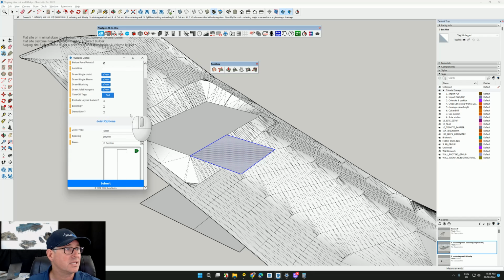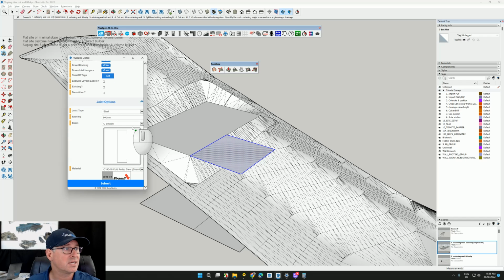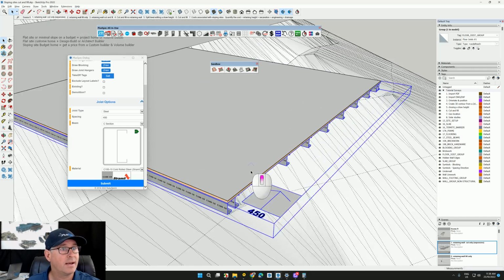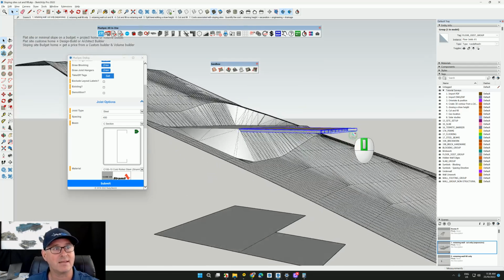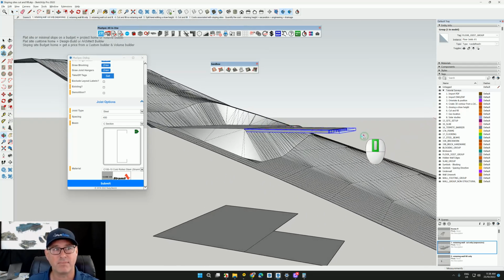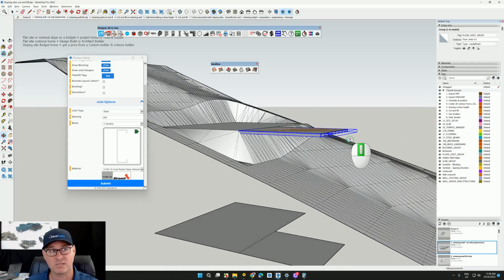We don't need a ceiling. Steel C-sections at 450 centers, say. And go submit. Right. Now I have joists in there. Now I can actually put steel across there and beams down there, because it's probably going to make a better solution for this particular site.